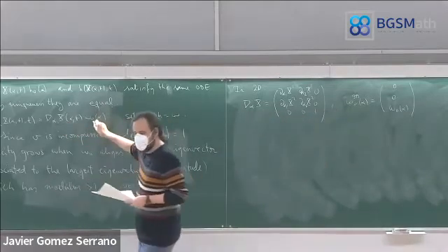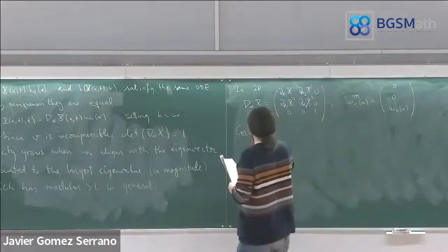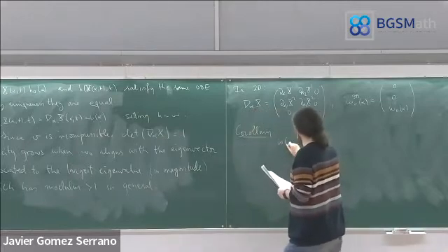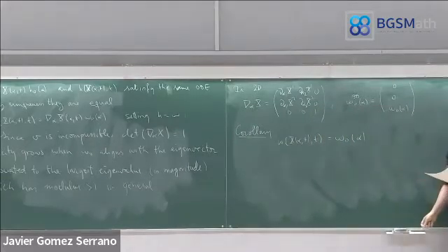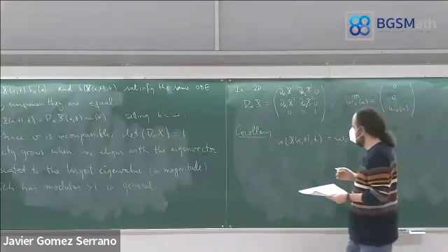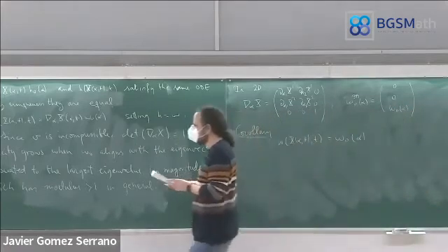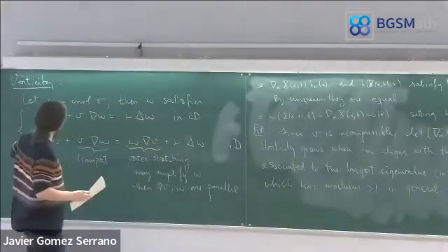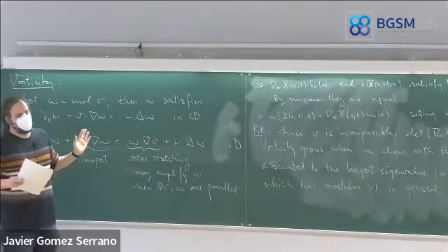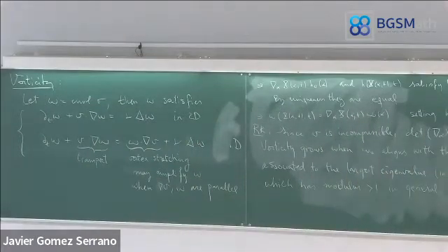Now, what happens? This times this is gone. If I just multiply, I get omega on the trajectory equals omega naught at the initial point. So vorticity in 2D is transported by the flow, no growth, just transfer. We can also see that if we look at the equation: if we ignore the Lagrangian point of view and forget about the dissipation, then vorticity gets transported by velocity, but there is no growth. It just moves, but the magnitude of the vorticity doesn't change.